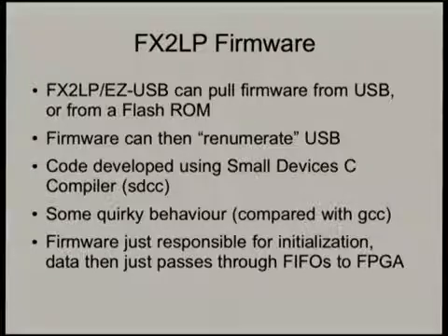So the code for the 8051 is developed using Small Devices C compiler, SDCC. It's different to GCC. It does some stuff differently, especially if you have strings and stuff that need to be pre-initialized. It actually goes and writes code that loads bytes into memory to initialize strings, which is just bizarre.